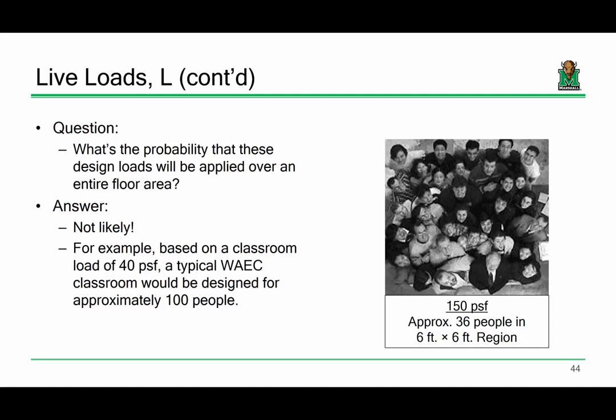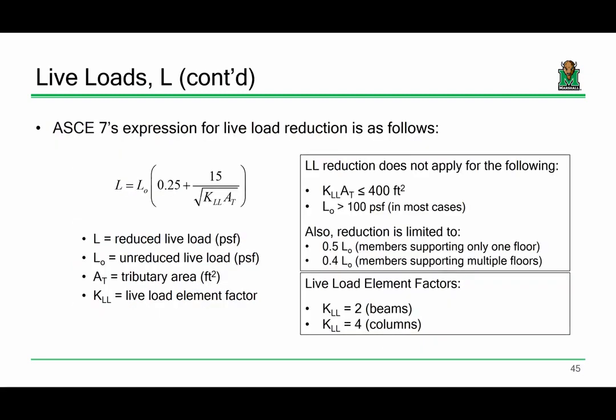Not likely. What we can do, and this is only true for live loads, is take the live loads that are presented in these documents and then reduce them for the probability that they're not going to see that load everywhere all the time. This is the fundamental expression for live load reduction.